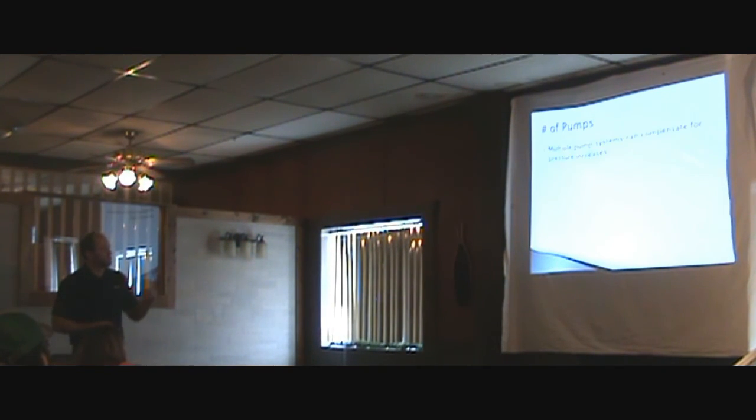The number of pumps is another thing. On multiple pumping systems, you have multiple pumps. Sometimes a simple pressure switch can drop your pressure down. I'm saying in a case where you have 5, 6, 7 wells, when your pressure goes up, you can just put a simple pressure switch on one of them and turn that pump off. So your pressure spikes, it turns off a pump, turns off another one. When it drops, it turns it back on. Simple setup to do that.